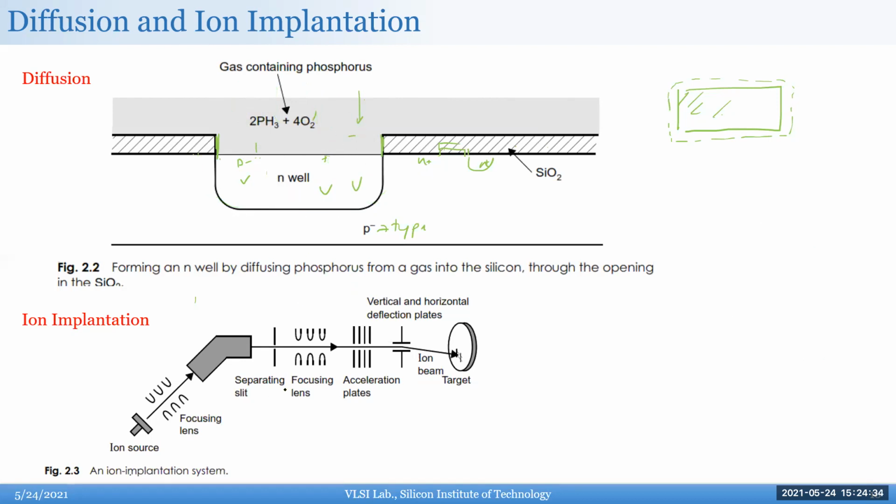So this photograph I've shown here, this wafer is here. You can see there's a small mask here, that's this opening here, basically by the silicon dioxide. So you have an ion source, whatever ion you're trying to create, phosphorus or whatever. And there's some electromagnetic focusing lens. It goes through sort of a waveguide for ions, and it just bombards it straight into the thing.